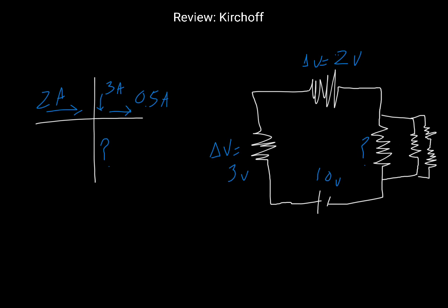The first thing we need to figure out is which direction the current is going. Because we have more current coming in than current leaving, we know that our answer has to be leaving, because the total has to be equal. We have 5 amps in, 0.5 amp out, so that means it has to be 4.5 amps leaving the circuit. What about over here on the right? This left one is the junction rule for Kirchhoff's laws. The right one is going to deal with the voltage drops.